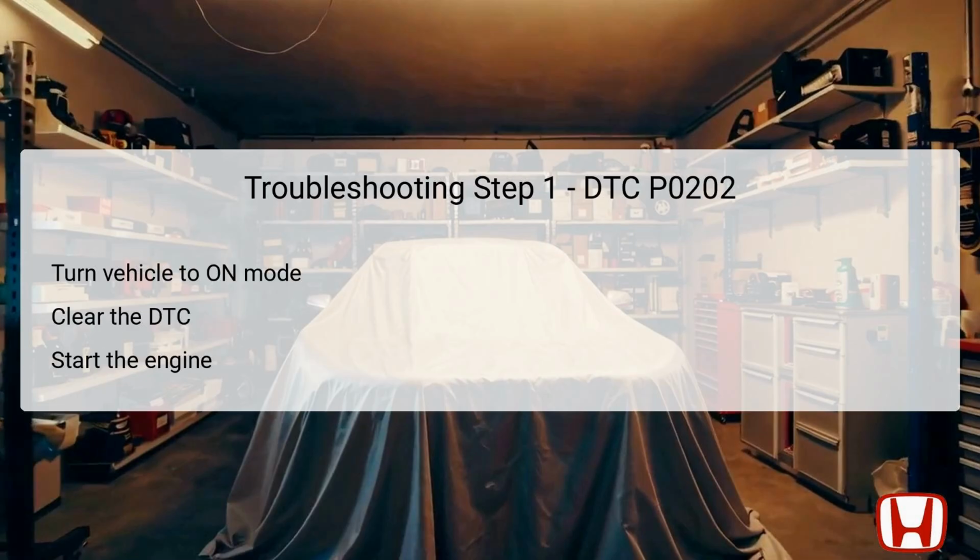The first troubleshooting step involves verifying the problem status. Begin by turning the vehicle to the on mode without starting the engine. Next, clear the DTC using the Honda Diagnostic System, commonly referred to as HDS. This step resets any existing error codes and allows for an accurate assessment of the current vehicle condition.